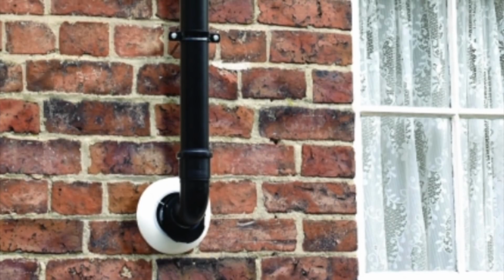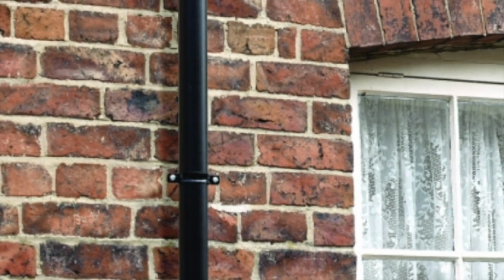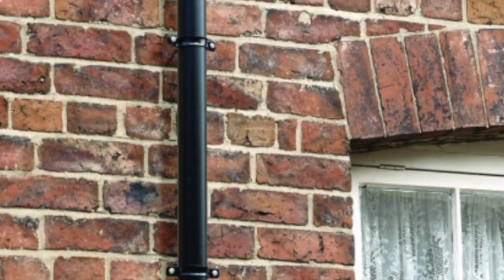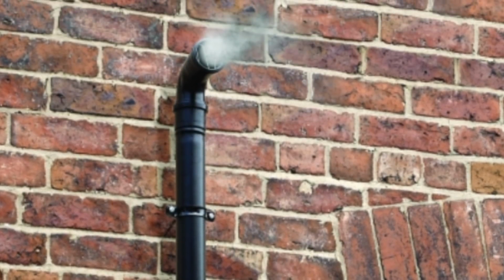Now the maximum height for a Plume Management Kit will all depend on the manufacturer. Basically what the manufacturers of the boilers say is you cannot exceed the actual flue length designed for that boiler. So again, manufacturer's instructions are key here, but why the heck would you want to go 2, 3, 4 meters high with a Plume Management Kit? They're only there to stop a pluming nuisance. If you go more than 2 meters off the ground, you are effectively reducing pluming nuisance.